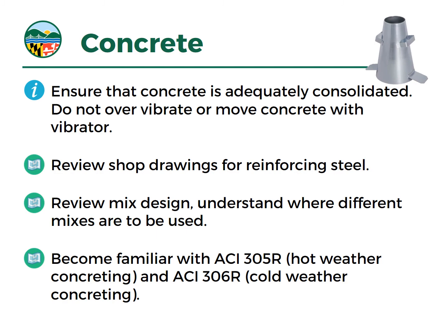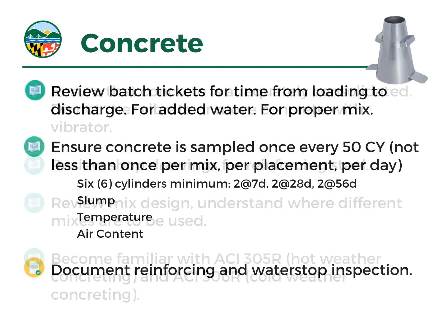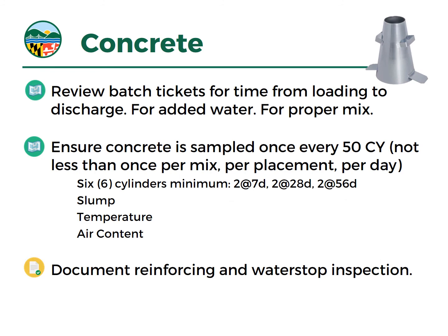We want to avoid any cracking or damage due to improper handling. Review those batch tickets. You want to make sure they're not adding excessive water between batching and delivery or batching and discharge. You want to make sure that we haven't exceeded the time requirements from loading to discharge, because you could get some initial set and poor quality concrete as a result.